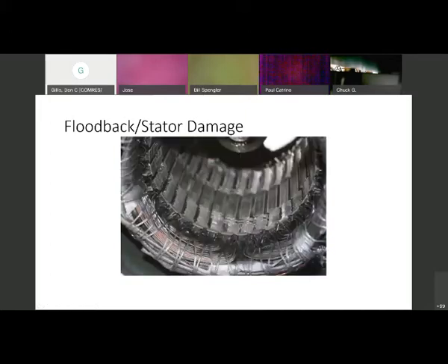And as it starts to sag, it gets close enough to this stator here, and it arcs out. Boom. Contractor comes up to the compressor. It's not running. Takes his voltmeter out. Calls your shop and says, hey, I need a new compressor. I've got an electrical issue. It may or may not get tagged, but if it does get tagged, that's what they're going to write down 9 times out of 10. But it started out as a mechanical issue, liquid floodback in this case.